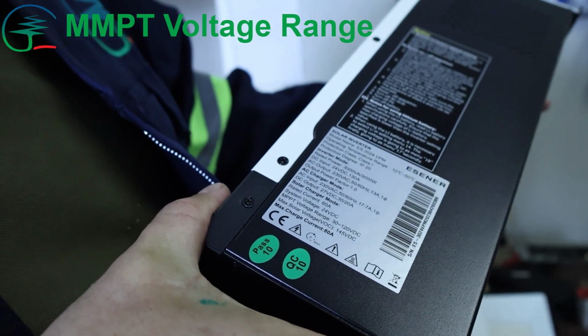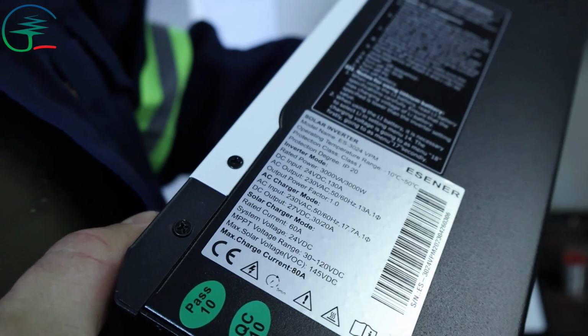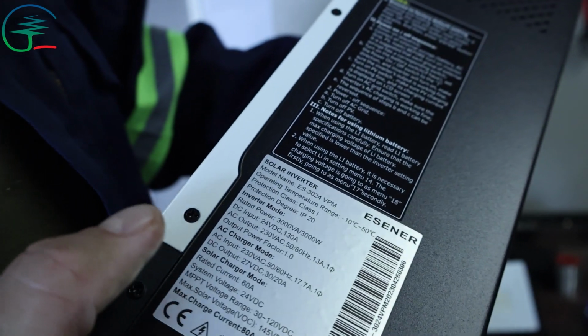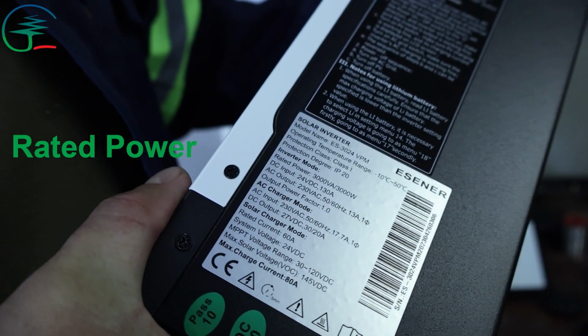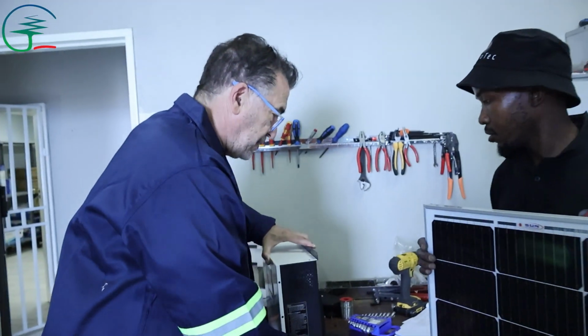The values we are looking for here are the MPPT voltage range, which is 30 to 120 VDC, and then the max charge current of 80 amps. The other thing you must look at is the maximum wattage of this inverter. It's 3000 watts. So those are the three things that you look at on your inverter.